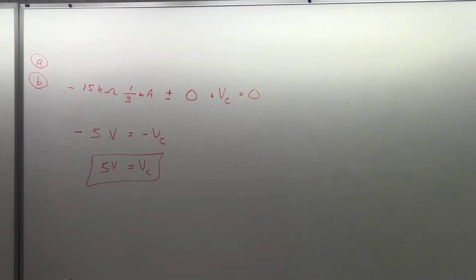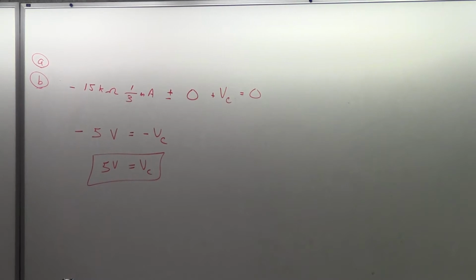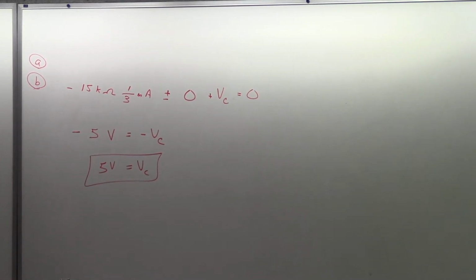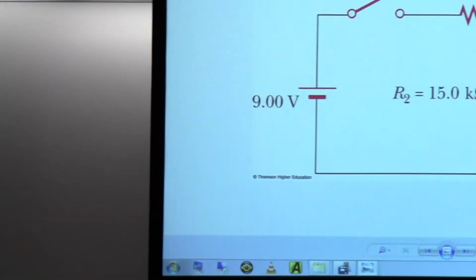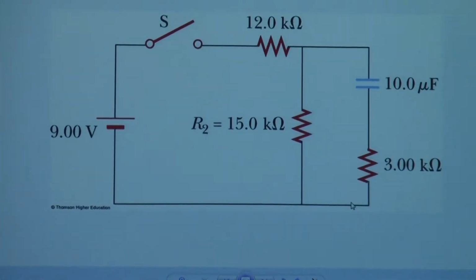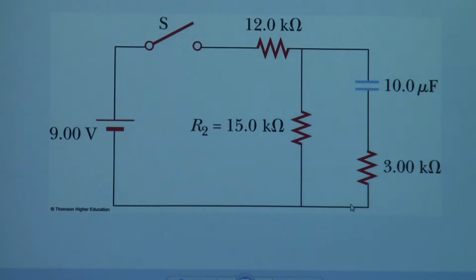And a big reason I picked this one is it's so tempting for beginning students to say that that capacitor builds up a charge until it's 9 volts. And that's really what I wanted you to see. It does not build up to 9 volts, the way those resistors are set up there, right? Depending on how the resistors are arranged, it could have been some other crazy combination.